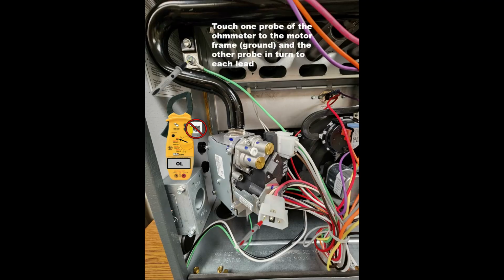Touch one probe of the ohm meter to the motor frame, ground, and the other probe in turn to each lead. So we would have the black. You always want to use your black for neutral or ground if possible. They always recommend that. So you're just going to hold that to that ground and test each pin and see if you have continuity to ground, and you shouldn't. If you do, you need to replace the motor.